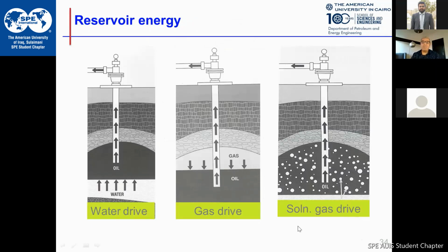So when we drill under balance, this is at a later stage, not during drilling. And of course, if there is no damage done, let's say to water drive mechanisms while we drill, okay? Because this is one of the mechanisms that results in the highest recovery when oil is displaced by water. Let's say no damage is done in the gas cap in the upper part of the reservoir, the gas cap area, then the gas cap gets expanded, and later on when the reservoir pressure goes down, the gas cap gets larger and definitely will contribute to production.